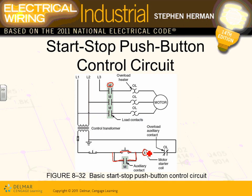So when you push this button here, guys, you energize the coil. Now the coil is hot, 120. It's a solenoid. It pushes. When a coil pushes, there's a mechanism that pushes contacts physically, mechanically. Then it closes its contact, and this air handling unit is running now by a push of a button.